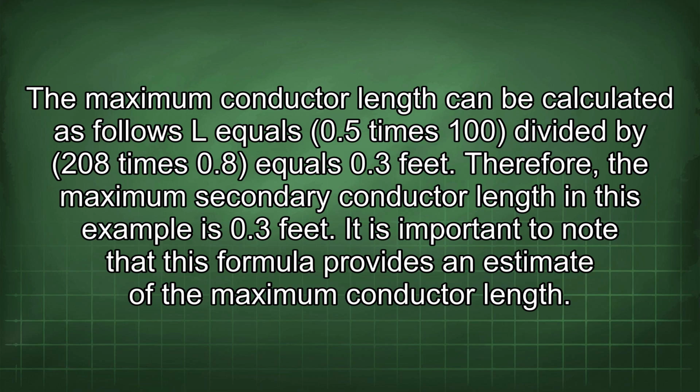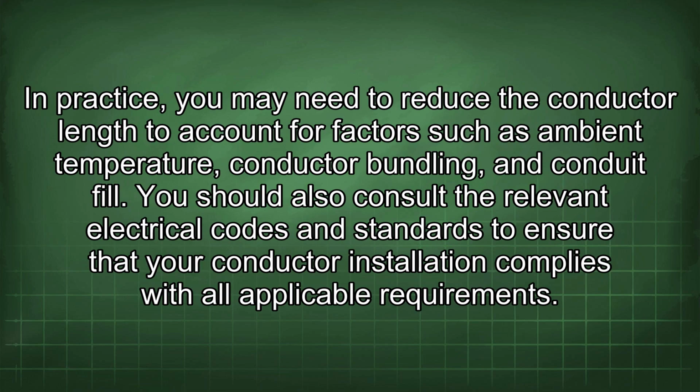It is important to note that this formula provides an estimate of the maximum conductor length. In practice, you may need to reduce the conductor length to account for factors such as ambient temperature, conductor bundling, and conduit fill. You should also consult the relevant electrical codes and standards to ensure that your conductor installation complies with all applicable requirements.